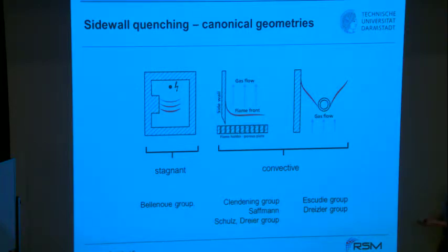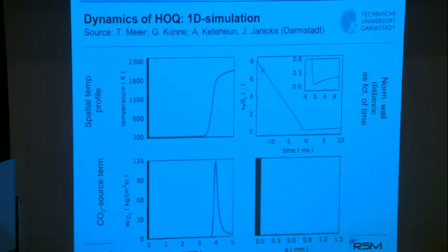You simply have a V flame. You take a flame holder like a ceramic rod, shown here in a cut. Then you have one branch of that V flame which is not interacting with the wall, and the other is doing that. And I think this is a very nice setup, because depending on the flow rates, you can also have a difference in the mean angle of interaction. So that is a device which is, I think, very useful.